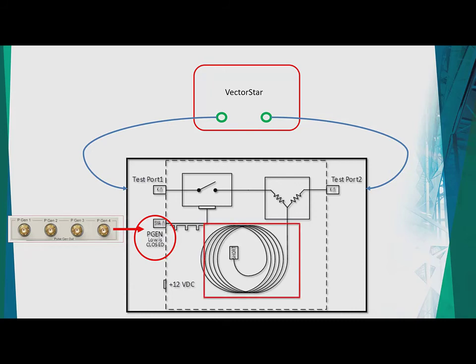You can also see that there is a long transmission line which is shorted at the end, so there might be reflections coming out, and these reflections will coincide with the outgoing signal, and they could combine constructively or destructively. That's why the pulse may have some falling edge discrepancies, and that we will show you as well.